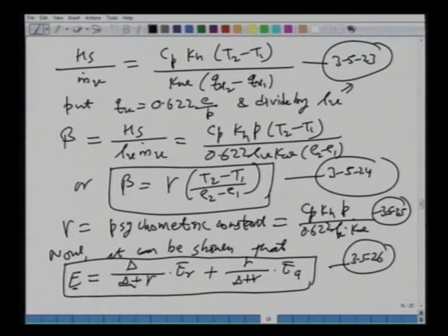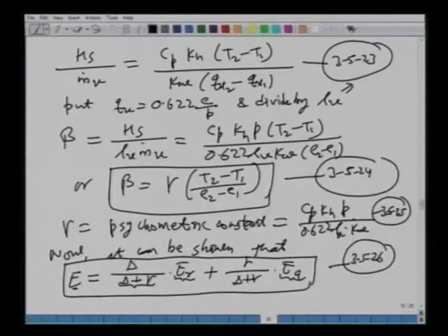Okay. So, in this equation what we are saying is that the rate of evaporation E, all right, has a certain weightage. Okay. This is E R. E R is what? E R is the energy balance method. Okay. This E A is what? E A is the rate of evaporation calculated using the aerodynamic method. So, we are combining these two and we are giving them different weightages, all right. One weight is delta over delta plus gamma, other is gamma over delta plus gamma. Okay. And you see that the sum of these two weightages is equal to 1.